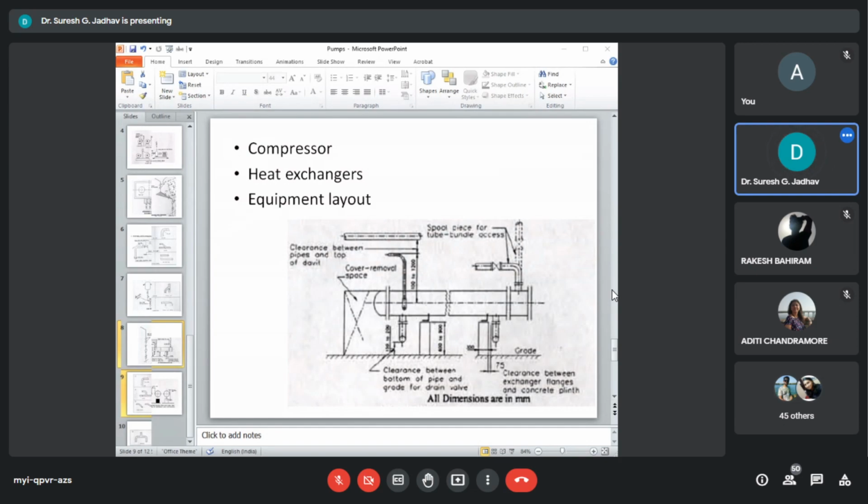While locating heat exchangers in a row, arrange the saddles to have a more economical overall design, that is line up or combine foundation or structure design. Further, a traveling gantry can be provided in such a case that can handle a row of exchangers. The heat exchanger shall be located in the equipment layout with respect to the fixed saddle, and the same is located closer to the head.